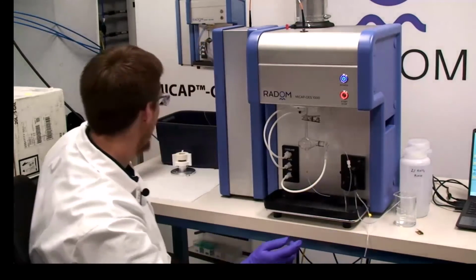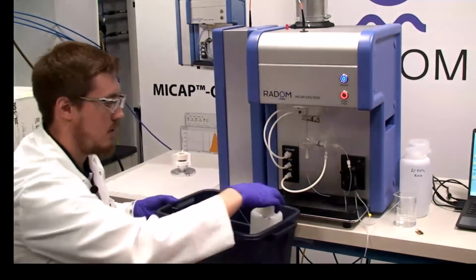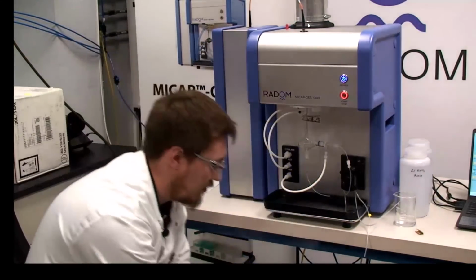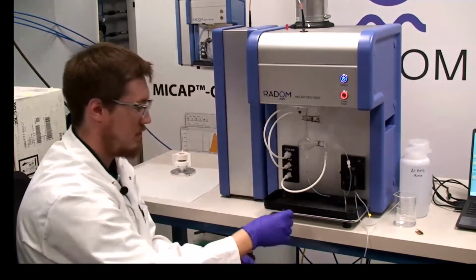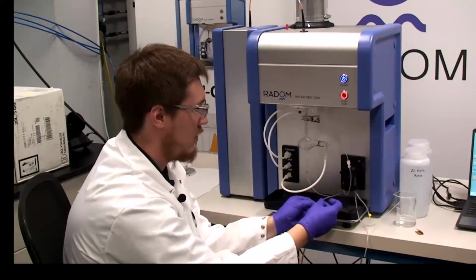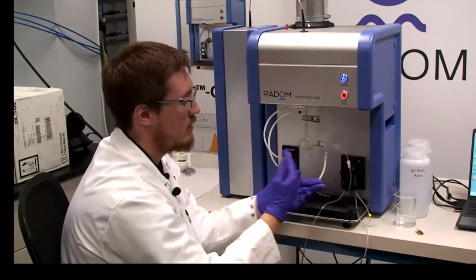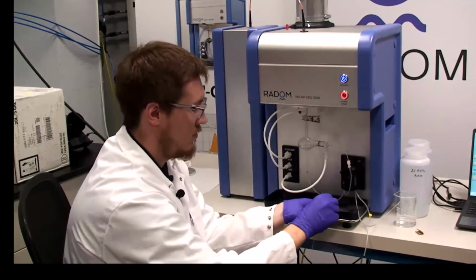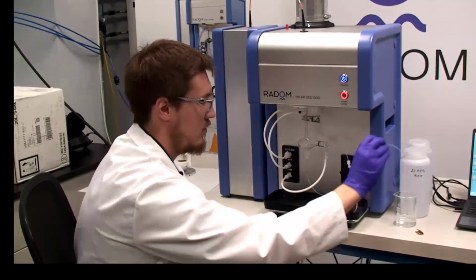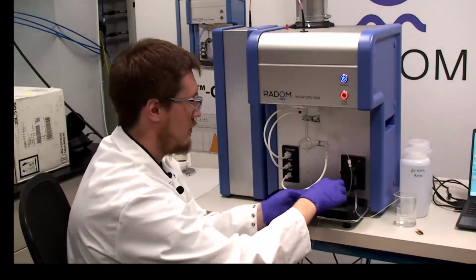For our waste, we have our waste container that I'm going to be setting down below the instrument, and the tubing that will connect to the end of the pump tubing here. It's important to note that the pump will be turning one direction, so you need to have your sample line and waste line oriented opposite each other. So one end of the waste line will go to the waste container, and the other end of the waste line will go to the base of the spray chamber here.